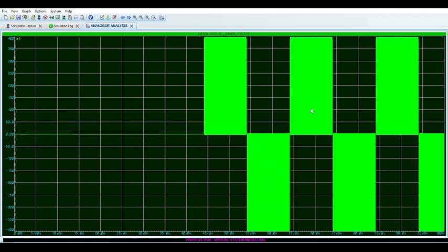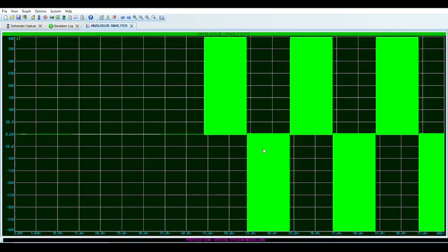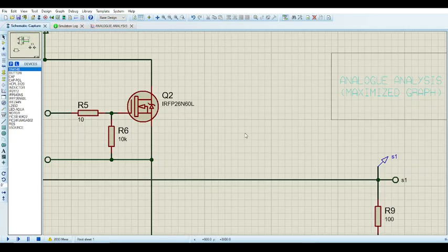And essentially, when you design your filter, you're basically just trying to filter this PWM signal out, because it's literally just high frequency stuff, 200 kilohertz. From what I've heard, you sort of have to filter 10 times less than that, less than 2 kilohertz, thereabout. Anyway,